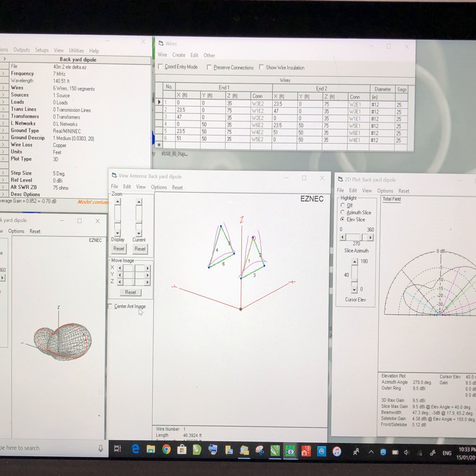If you find that you're really struggling with this, you can maybe take a look at the length of coax you've got, and you can always increase the length of coax. The increased length can be coiled up either at the shack point, the base of the mast, or the tree, or the tower, and this doesn't do any harm. This will act as a bit of a RF choke type balun situation, so that can help stop currents from flowing down the outside of the coax, and that may help to get a match. But generally speaking, you can normally work with what you've got, and it's just on the odd occasion you might get a length of coax that just doesn't help you with the match on a certain frequency.